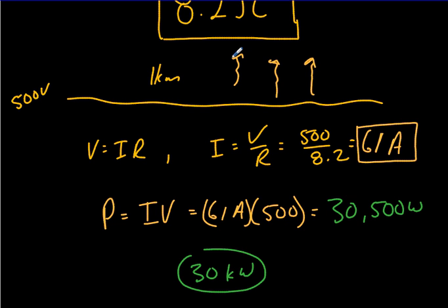Another interesting thing is you run it as DC voltage at very low current. So one way to transfer electricity a long way is run it over DC. That seems to decrease power loss, but if you amp this up to incredibly high voltages, but at very low currents, the power losses decrease quite significantly.